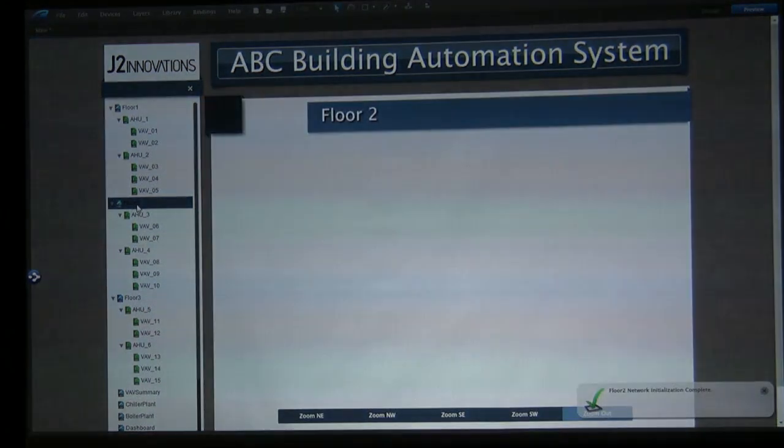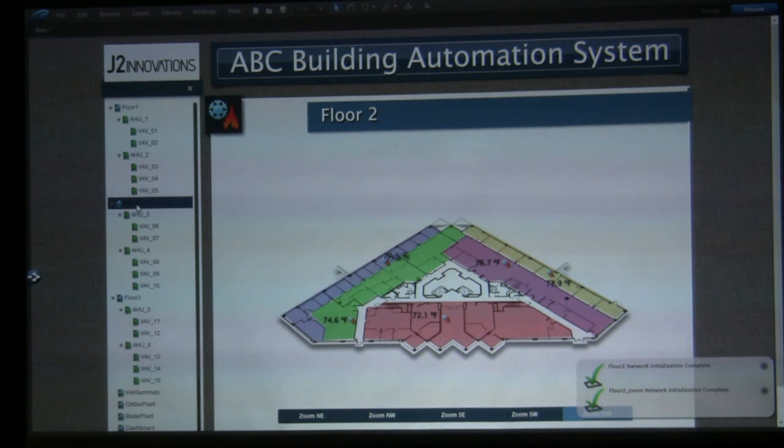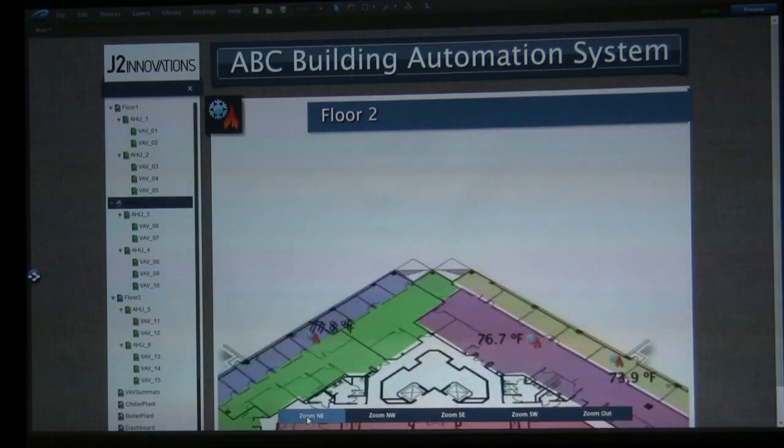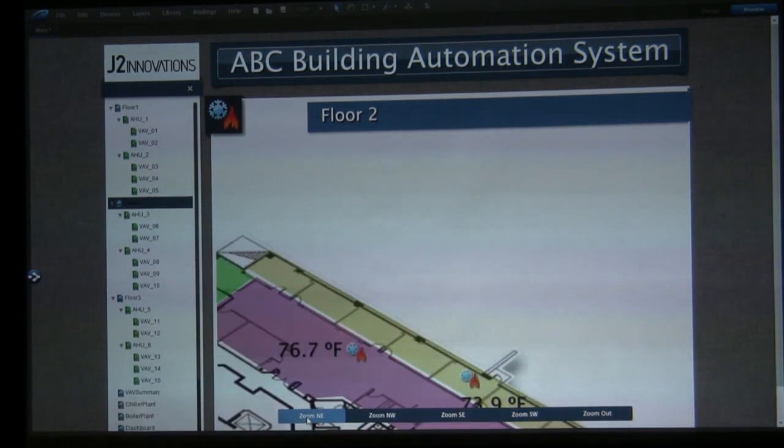Let's take a look at floor plans. This is one of my favorites. If you ask your SIs how much time they spend doing floor plans with the hyperlinks, particularly big floor plans that might be broken up into quadrants or even more, they're oftentimes hyperlinking from the west to the east, from the north to the south, and as soon as somebody renames something, that hyperlink breaks. We solved that problem by introducing an action called zoom. So check this out. Instead of dividing this floor plan up 4 times and making 4 PX pages, we just make one floor plan graphic, and then we fire off an action on this button bar, and that action then goes to a zoom window.